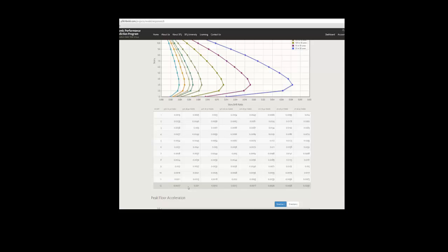The typical simplified method approach also has default variability values for story drift and acceleration. Those would still be used, but you would be overriding the mean response values. So I would call it enhanced simplified method, but frankly, it's quite enhanced. Really, the only thing you're assuming is variability.